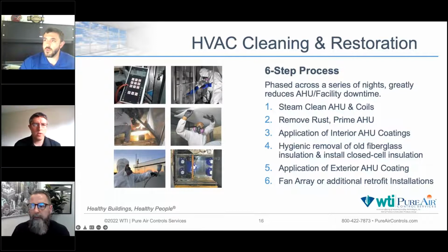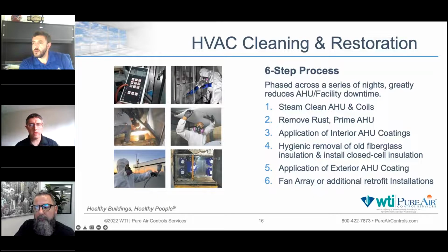If I can interject too, just for everybody watching from a facility standpoint, I know we're talking about these steps and different aspects of hygiene, but the little things I always like to point out, when we're going from the assessment to actually applying some of these, as Frank said, not every air handler is the same. But if you steam clean several units, don't just think of it as the unit itself, but what effect does that have down the line on your chiller? Just as one example, right? How expensive are chillers? How expensive are compressors? As we start to do things like cleaning, think of it beyond just the air handler, but how the other systems are affected in energy, in life.